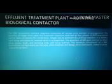In effluent treatment plants, the rotating biological contactor RBC procedure regularly comprises various units worked in arrangements. The number of stages depends on the treatment objective, with 2 to 4 stages for BOD removal and at least 6 stages for nitrification. Stages can be provided by utilizing baffles in a single tank or by the use of separate tanks in series. The suppliers of RBC equipment differ in their disk designs, shaft and packing aids, and setup layouts.